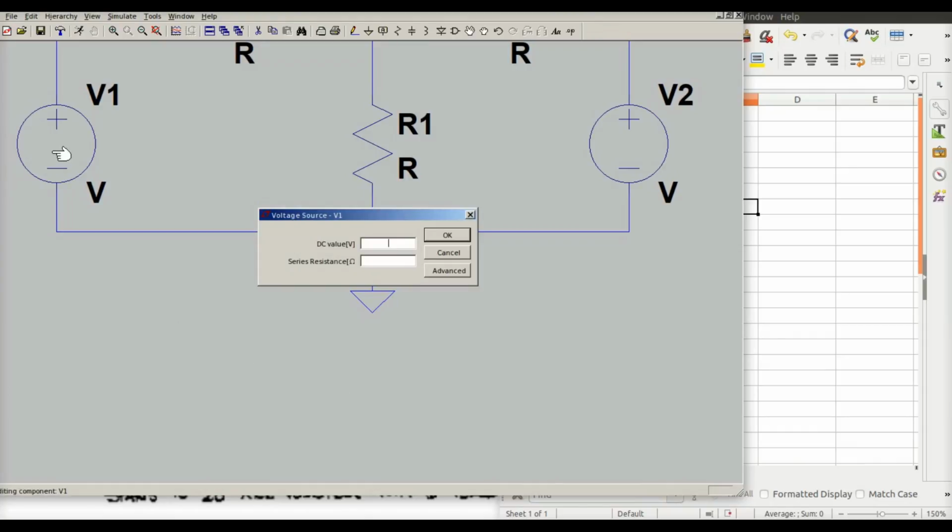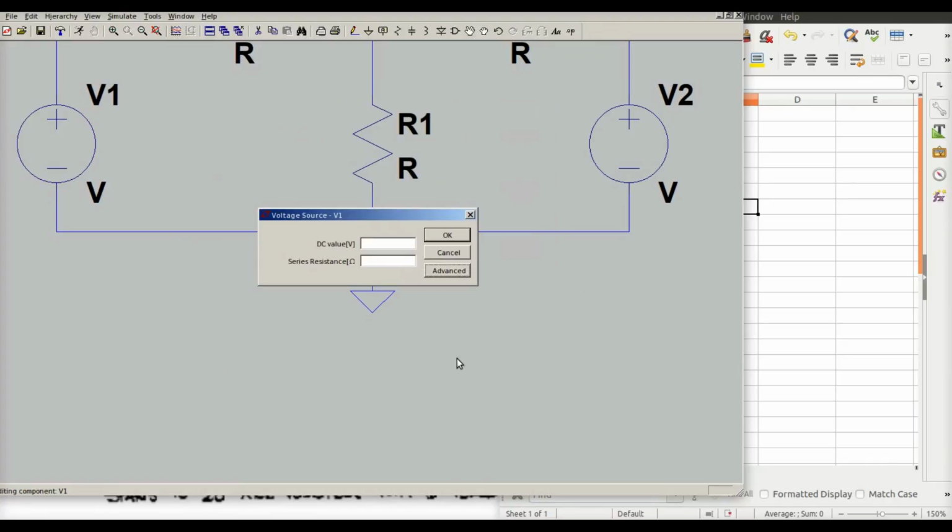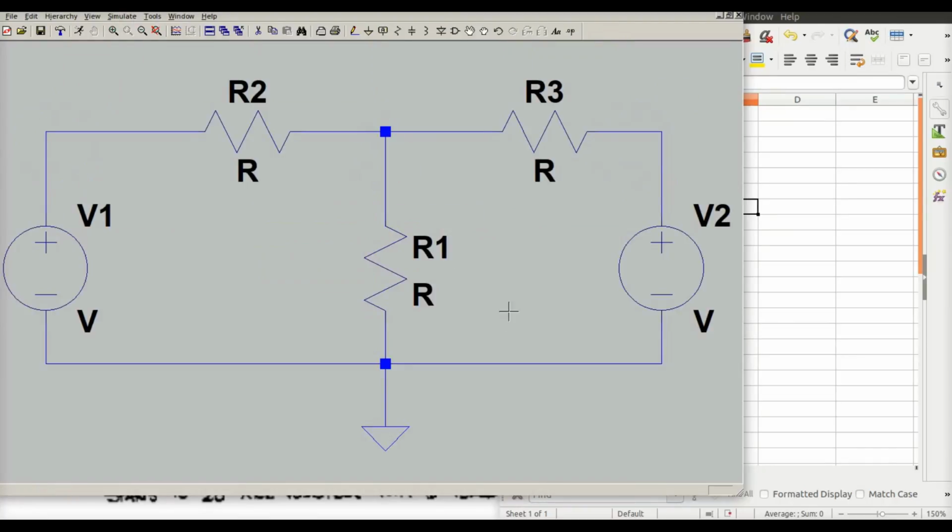Okay, now I'm going to set the first voltage waveform, and I'm going to show you transient analysis first, so I have to set it up as a sine wave. When I do superposition, I would set it up and do just AC analysis on them. And when I do superposition, I have to do each power supply separately.